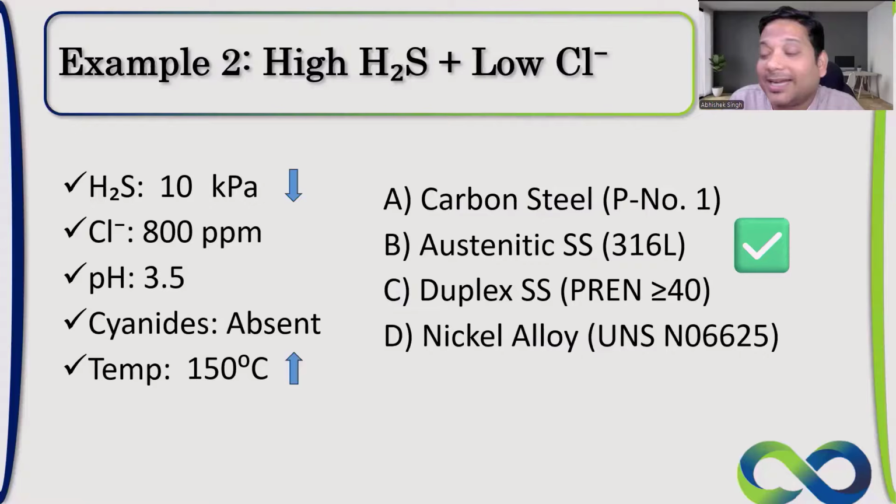From 100 kPa, directly it will go down to 10 kPa. I'm playing at the limits. Okay. So 150 degrees Celsius is the limit if my partial pressure is 10 kPa of H2S. So if I increase the temperature just by 30 degrees Celsius, from 100 directly, I'll come back to 10 kPa. I will not be able to take more pressure than that.